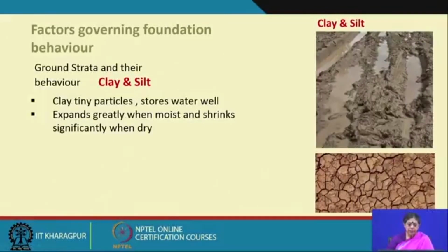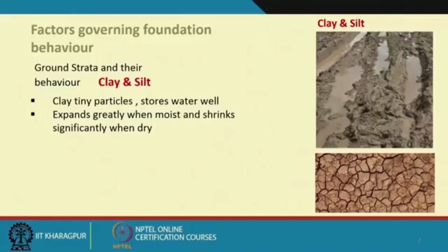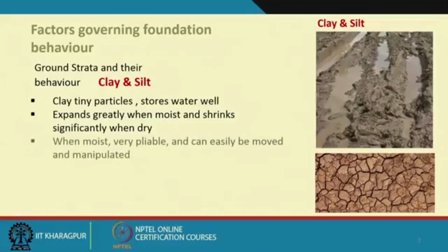So, its behavior changes when it is moist or when it is dry. It expands greatly when moist and shrinks significantly when it dries, so you can see that when it is dry there is a crack which has developed. Now, there is a change in the pore pressure which developed because of the water which is retained, or if there is a pressure coming, then the water is going out of the pore. So, the bearing capacity changes. That makes a difference.